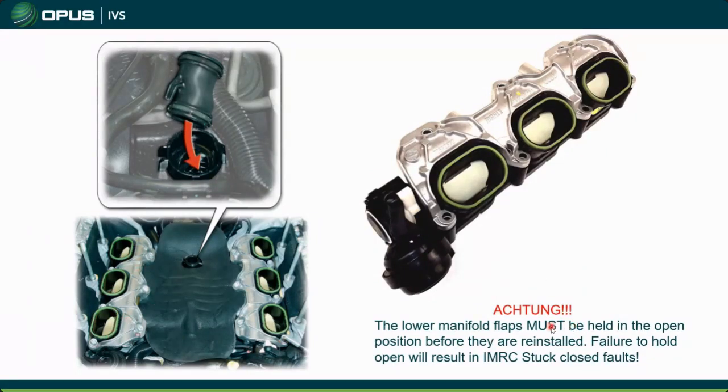So if you learn one thing from this class, let it be this. Do not put this back in until you hold open these valves. I like to just hold them open with my fingers, but I will warn you, you're going to want to open them all at the same time. Do not try to open all three of these flaps by just pushing on one of them, because you will break it.